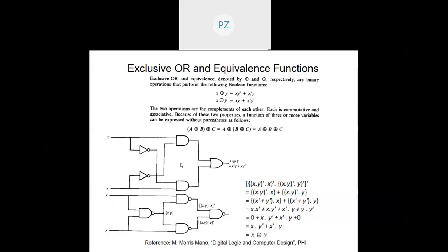So this is the straightforward implementation in the AND-OR form that we are already familiar with. But over here, if you see, it requires 5 gates in all, right? One OR gate, two AND gates, and a couple of inverters. If I try to get these inverters using a NAND gate, then the hardware complexity will even go further up. So 5 gates are required this way, provided that the complements of the functions are not given.